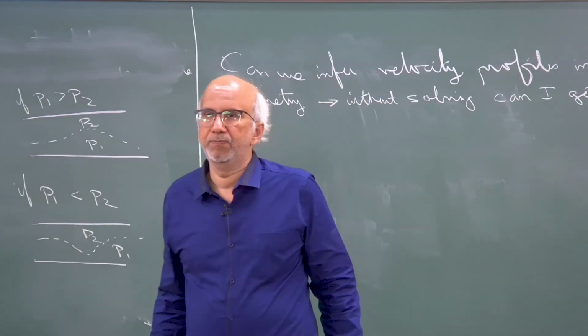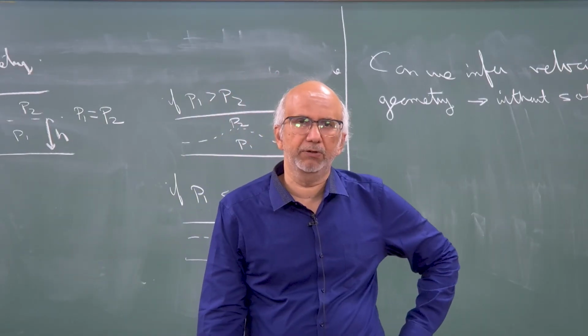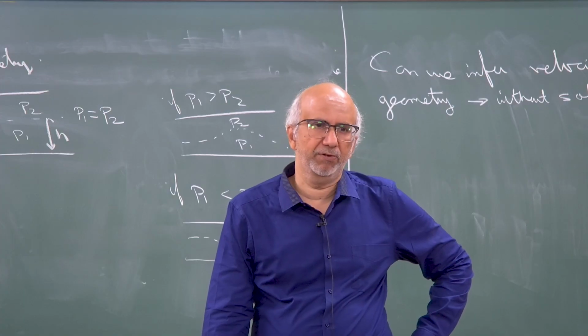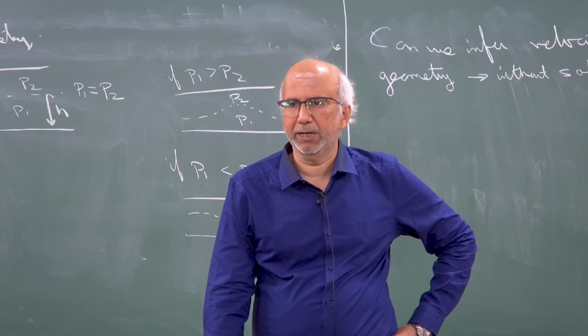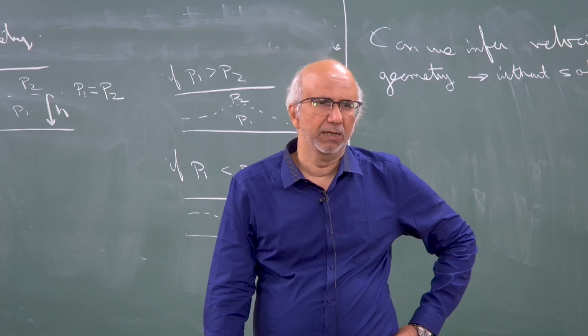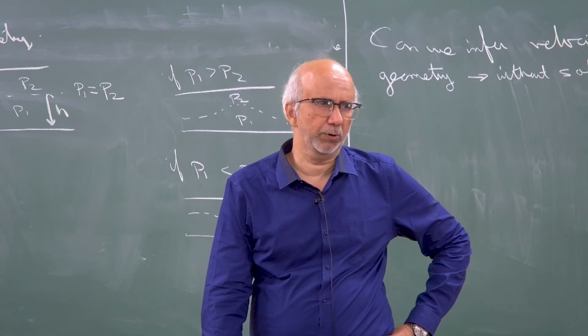Now, you remember the derivation, we got the velocity for the first fluid and the second fluid, they were both varying as y squared. I mean, you integrated the equation 2 times and you got u1 of y is dp by dx y squared by 2, both of them were y squared by 2, okay.